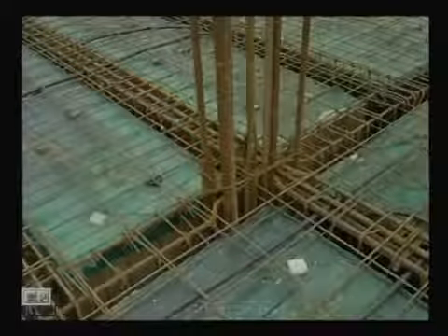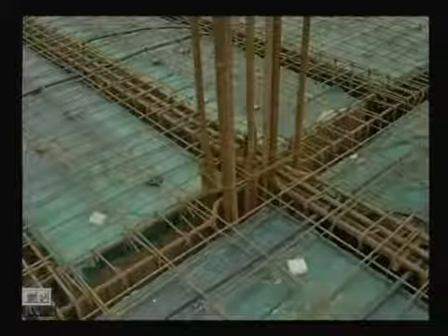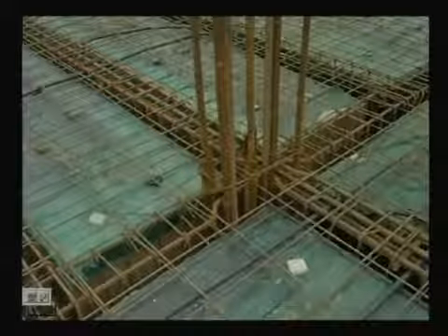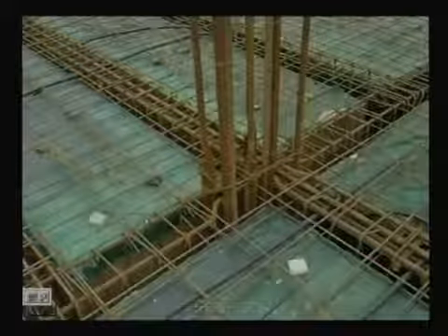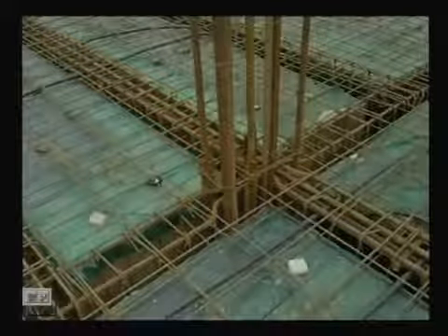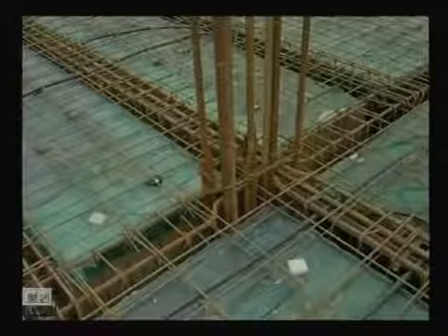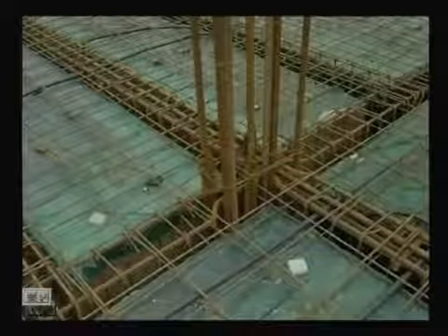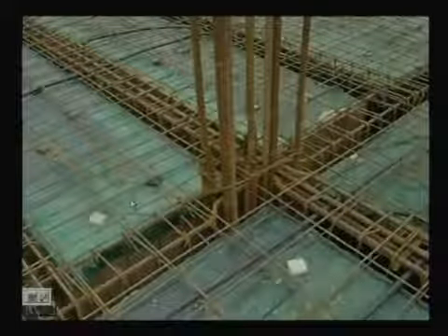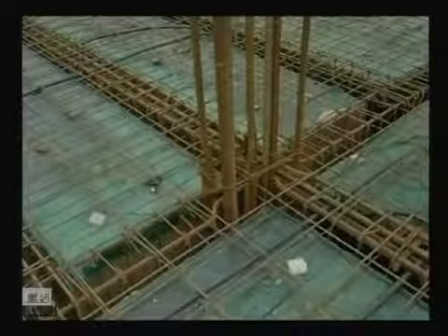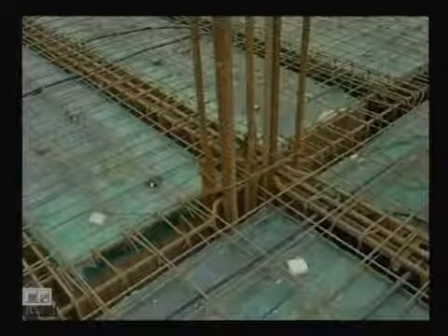You see this is the top of the slab, this one is your slab, the reinforcement, and you are providing this one. Please note all those things provided here give clear cover, because otherwise it will just simply lie on the floor of this formwork. So you will not get the clear cover. So you have to provide that clear cover here, here, like that. You have to give that clear cover in different places.